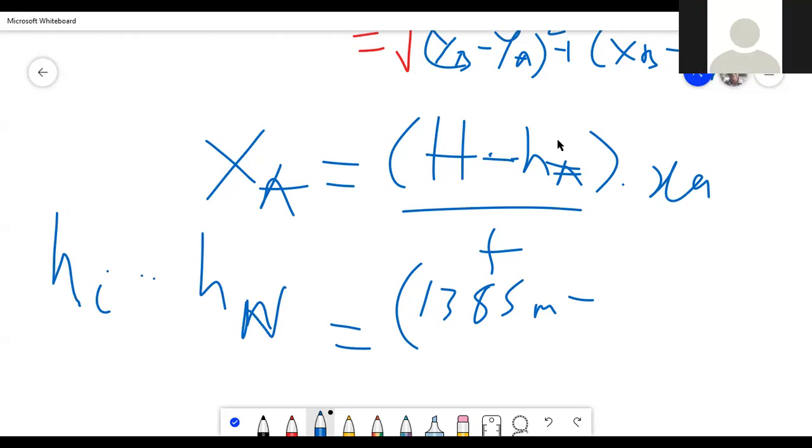These points can be infinite on the photograph, but we are only interested in probably the top of a church building, the ridge of a church building, or the top of a hill. The formula is for a particular point. It only calculates the coordinate for a particular point using the height of that point on the ground.